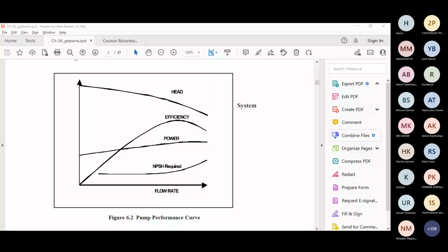Whereas your pump's discharge pressure, suppose there is a 30 meter head pump. If you are pumping from 0 to 30 or 30 to 60, what happens there? Your discharge pressure changes. Sometimes it can be 3 kg, 6 kg, and even 9 kg, because you are increasing the suction pressure. And the head is basically the total differential head. So head is always the same; discharge pressure might change, right? Clear? So head is always the same with respect to the unit with which the vendor is providing.